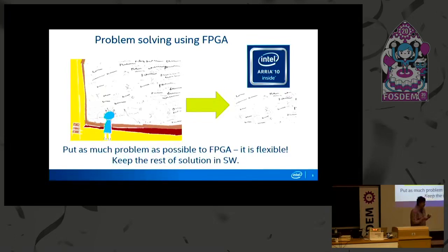The solution to this problem is, for example, moving some data, some counters which are the most painful, not all counters, yes, but the more painful ones. We sometimes call them aggregate counters, which must be handled by many cores, to the hardware, yes, which can solve the problem because the hardware processes the data serially, but the software does not have this problem again, and the software can do most of the processing in a parallel way, using the cache very, very efficiently, yes. This is some kind of the problems, yes.